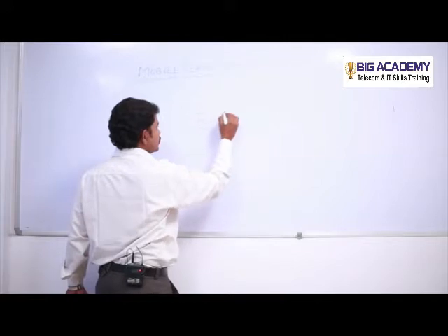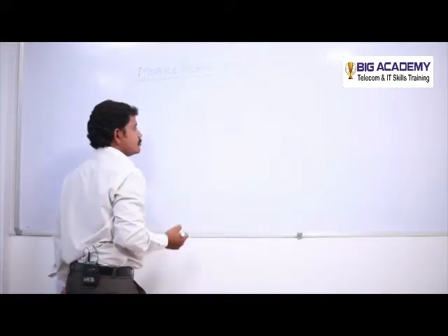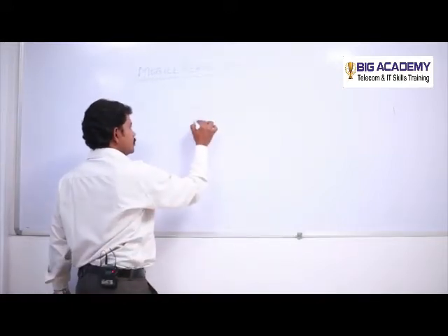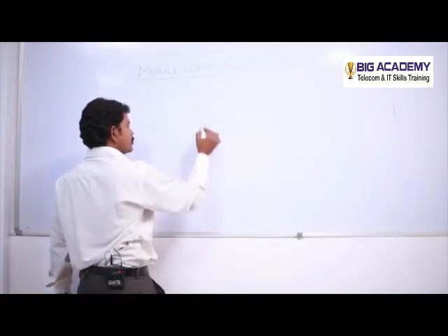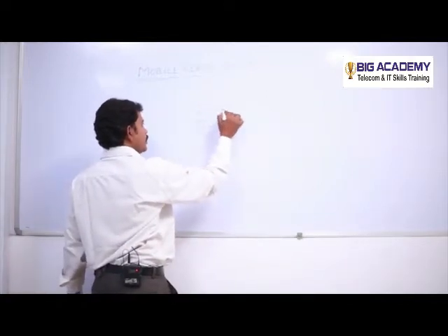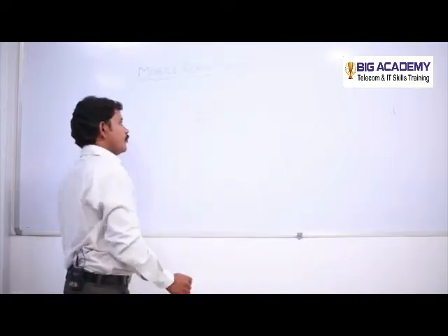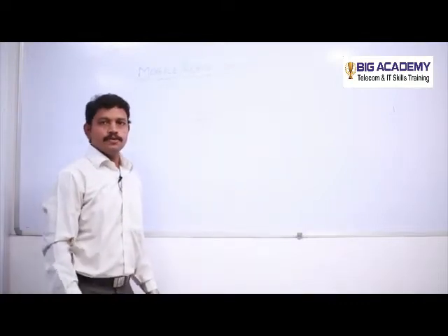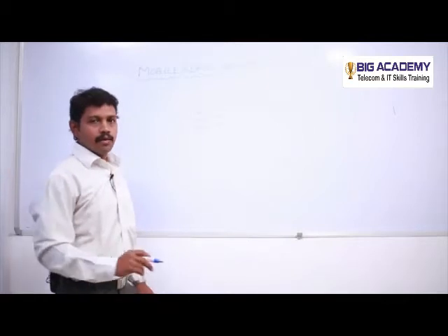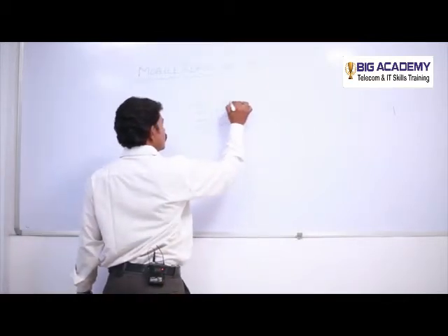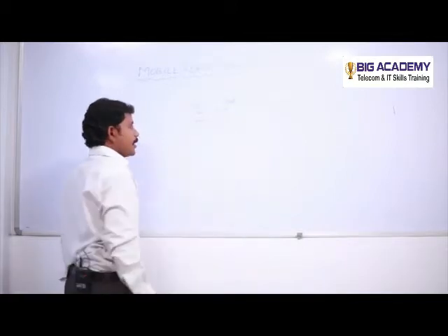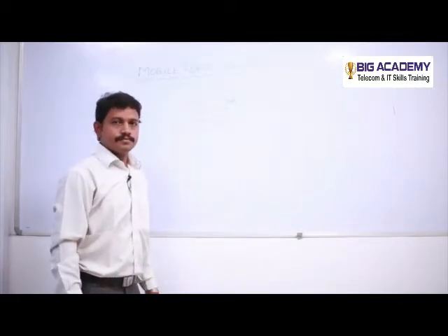It has 6 points in your SIM, right? 1, 2, 3, 4, 5, 6. You have to check pin number 1 and pin number 4, which are voltage and ground. If the voltage and ground are good, that part should work fine.